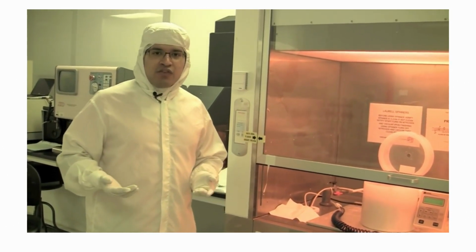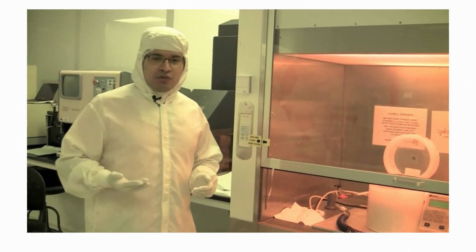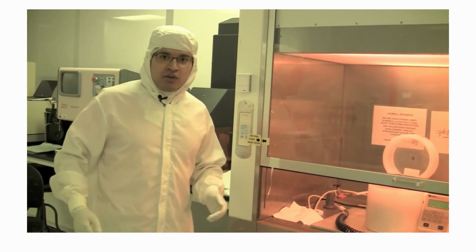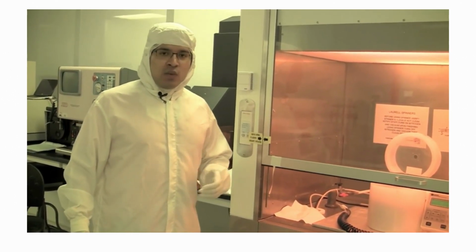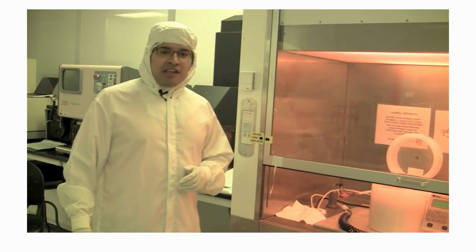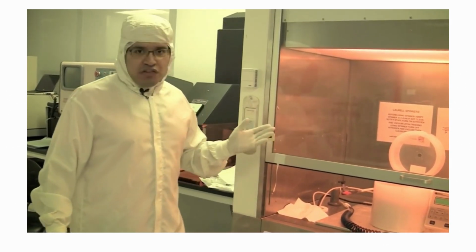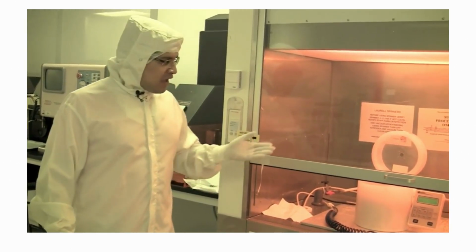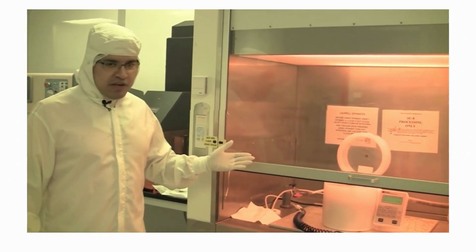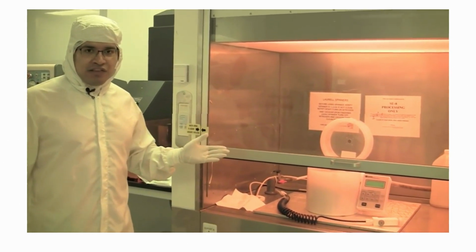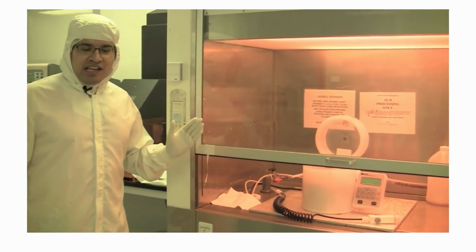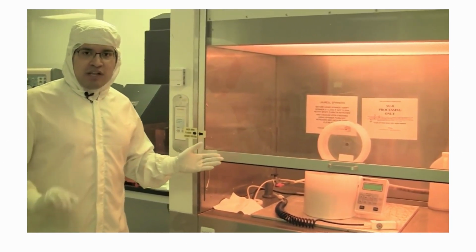Now in our facility, we have two separate rooms for each kind of photoresist. In this room, the hot embossing room, we only do negative photoresist. We have another room down the hall that is dedicated to positive photoresist. The same tool is used in each case. We have a Leroy spinner right here. The Leroy spinner is designed to take your photoresist, put it on a substrate, and evenly distribute it so you have a nice uniform layer.